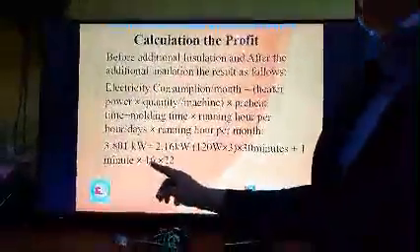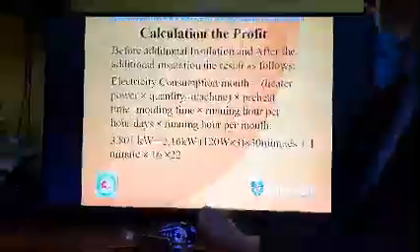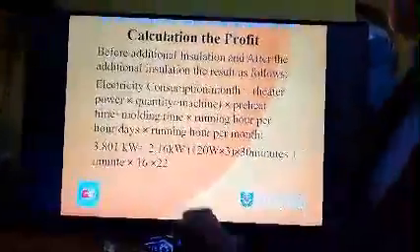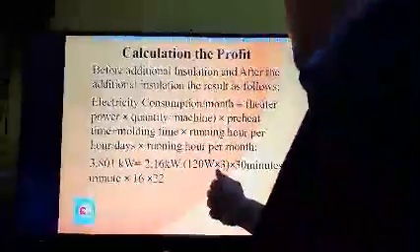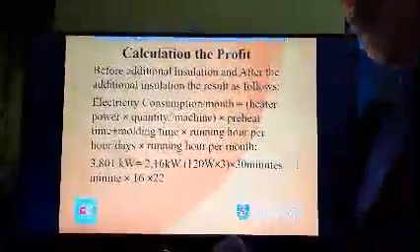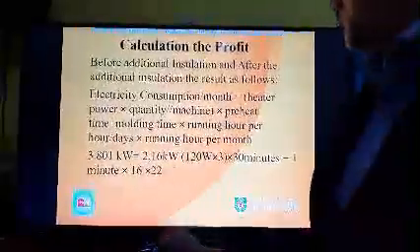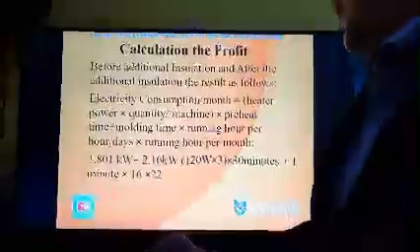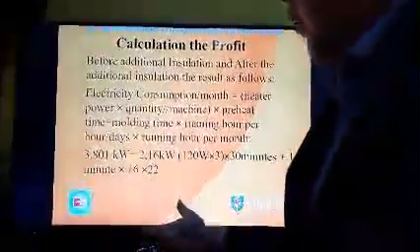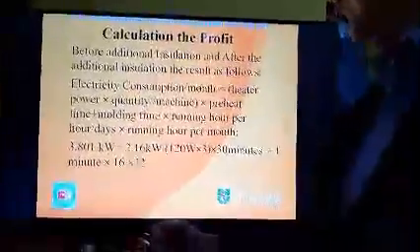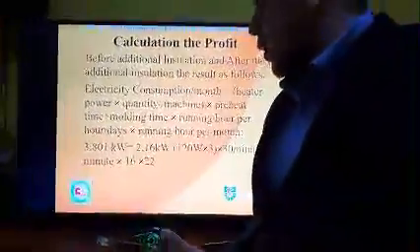So we can see here, before we gave the insulation, it cost around 3,800 kilowatt hours. It comes from 2.16 kilowatts, which came from 3 times 120 watts of heater usage, times 30 minutes of preheating plus 1 minute of cooling down, times 16 production hours per day, times 22 running production days per month.